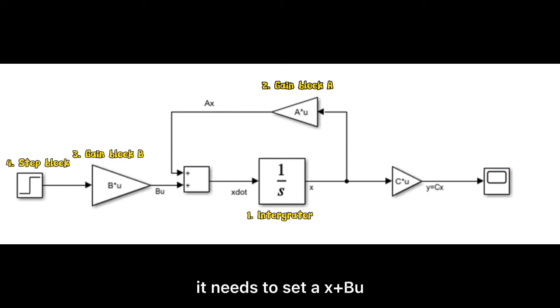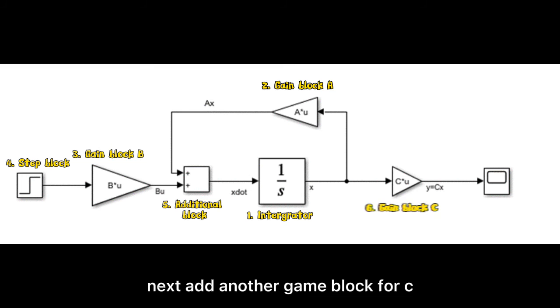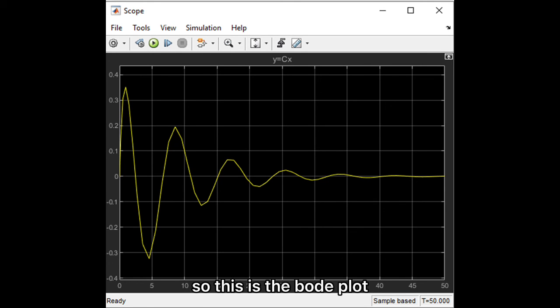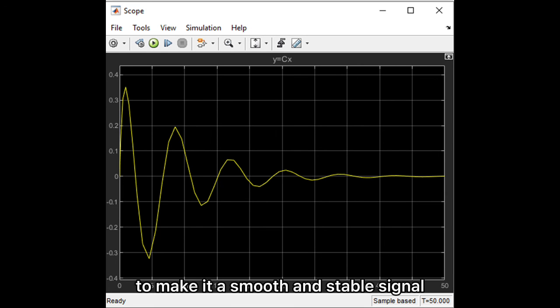For this operation, it needs to set Ax plus Bu, so it is necessary to add an additional block. Next, add another gain block for C, which is y equals Cx. Finally, add a scope block and run the Simulink and both plots will come out. So these are both plots from the Simulink block. But before running the Simulink, we need to make sure all the parameters are in the workspace. The scope will show both plots after running it. Before that, set the stop time to 50 seconds to make it a smooth and stable signal.